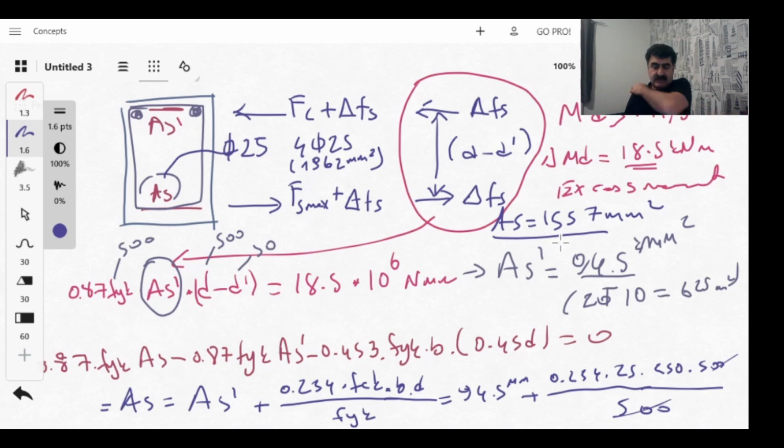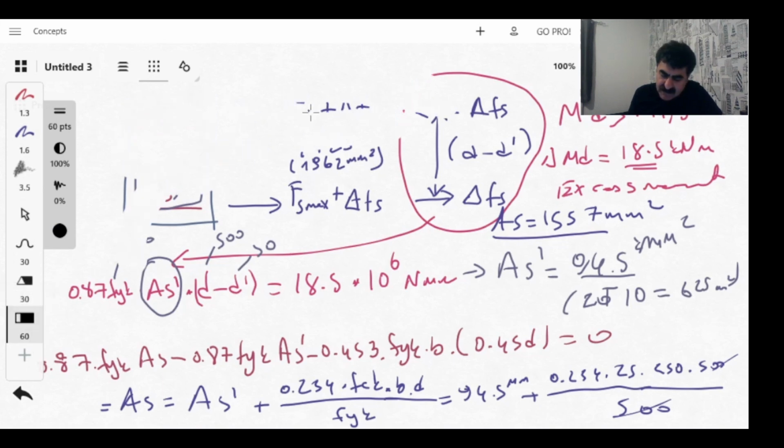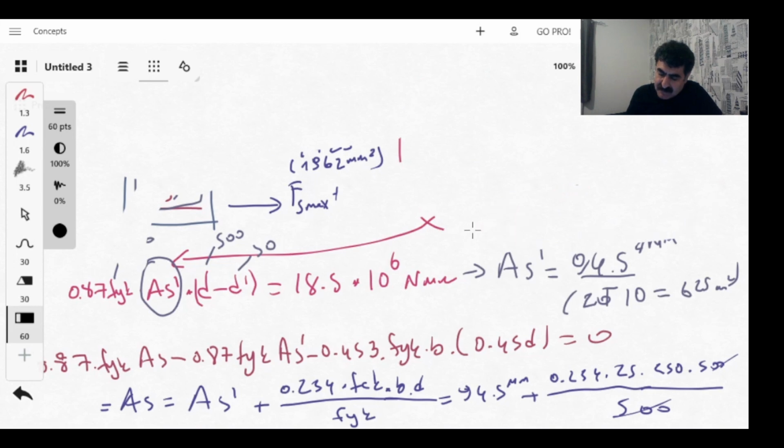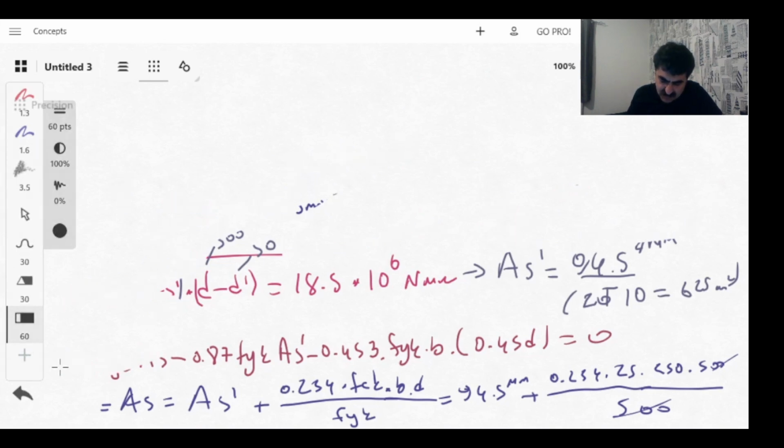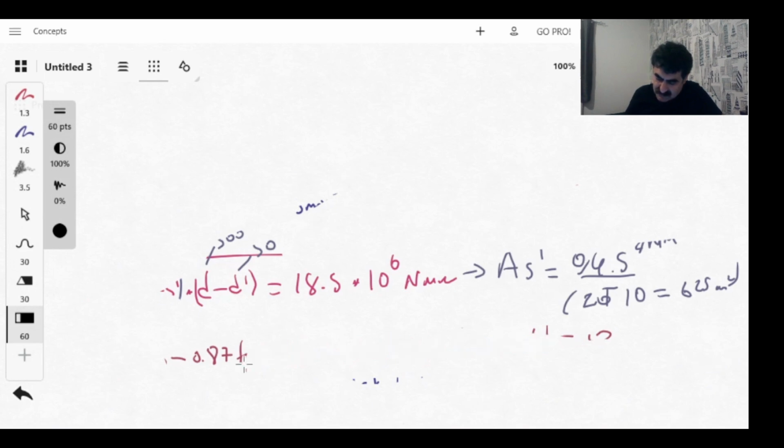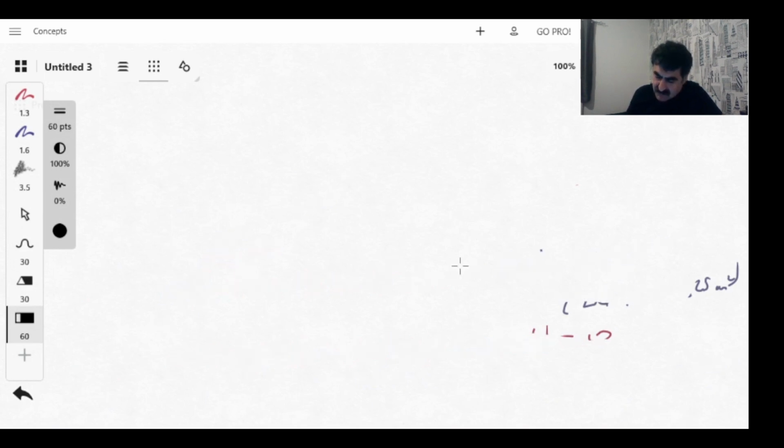Now I am going to delete all the area and then draw the sketch, which is important. The only communication between you and the labor is your sketch. Your sketch should be correct as well. So let me draw the sketch. So this is section C. Section C says, sketch the cross section of the beam illustrating the position of the chosen bars. Secondary reinforcement stirrups need not be shown. Okay, stirrups, but we are going to show it, no problem.